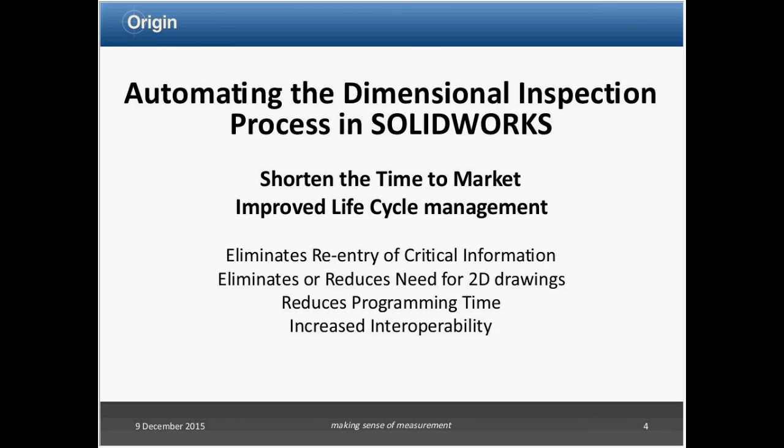Back to you, Cease. We have another one on the topic you were discussing. How are scan data points assigned to tolerance and datum features? I guess that's all part and parcel of our substitute feature. When we extract the information from the scan for those points we've created, we automatically assign that to those features. For example, for holes and circles from scan data, it's what we call substitute feature generation, where we can actually create a circle measurement from that scan data as far as results go.